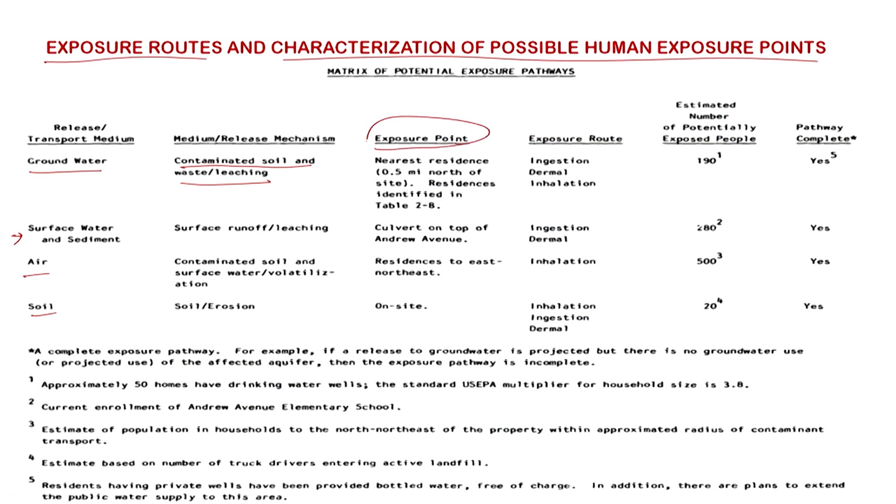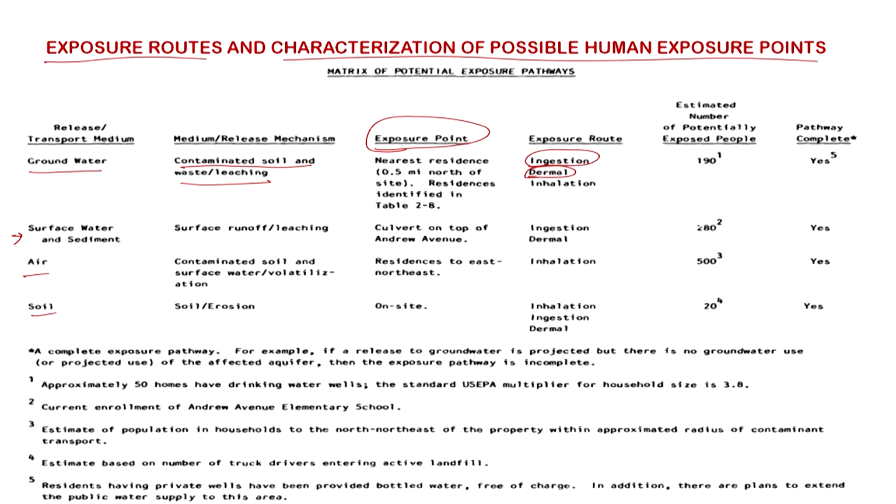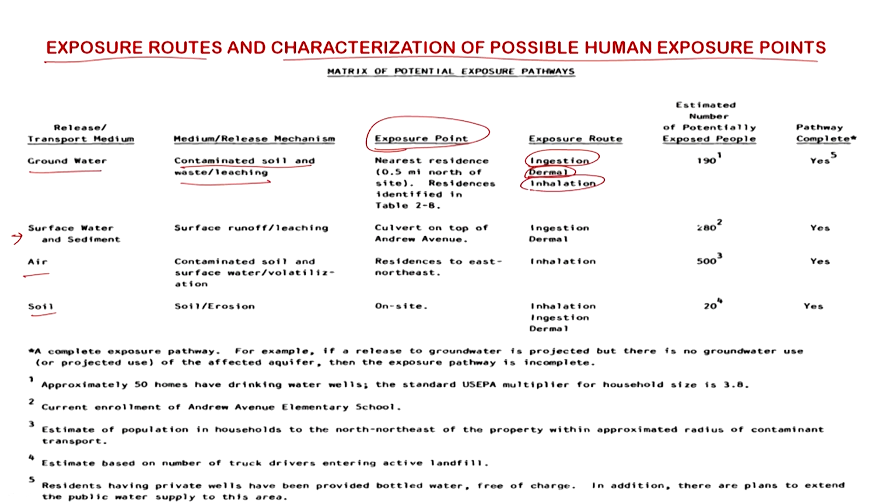And then what next? We have the exposure point: how or where are the humans being exposed? And what is the exposure route? For example, groundwater ingestion, as in they drink the water. Dermal, as in they bathe with this particular groundwater that is pumped out, so contact through the skin and absorption through the skin. And then inhalation, let us say while they are cooking with this groundwater or coming in contact with it. Depending upon how volatile the compound is, it changes phase from the water to the gaseous phase, and then I can breathe the compound and thus be affected by it.